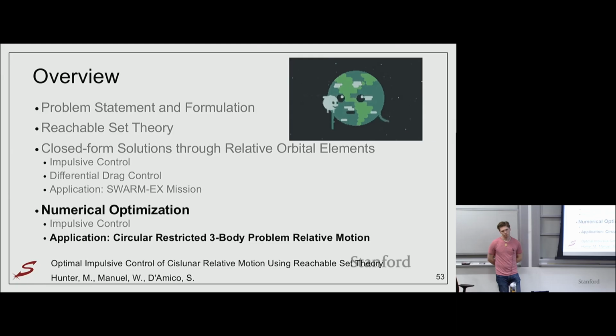So you derive them for a certain geometry of the reachable set, which, however, changes with the length of the control window. Instead, a numerical optimization algorithm, which is guaranteed to converge within a tolerance prescribed by the user, can work with sub-orbital reconfiguration. So that's one of the key reasons why we have a numerical method, because it's general.